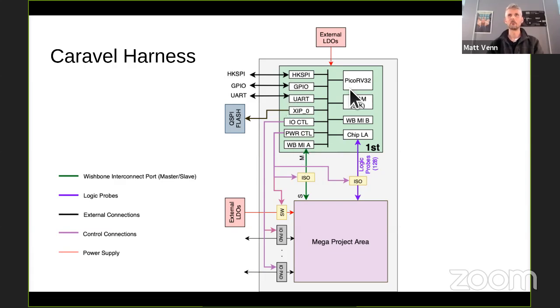So we've got a RISC-V processor on there, some RAM, some I/O, the ability to read programs off the flash. We've got a logic analyzer built in, a Wishbone bus, a whole bunch of support stuff. So if you add this design for testing, we can read in or set things using the RISC-V processor. And then this is where your design is going to go.